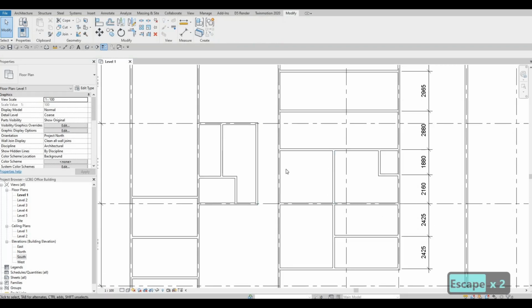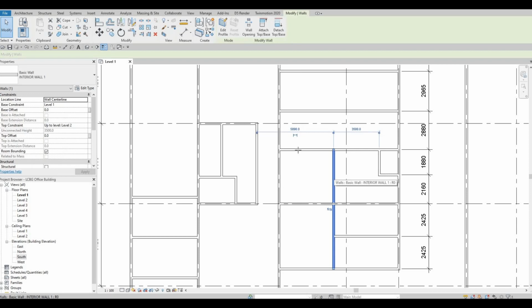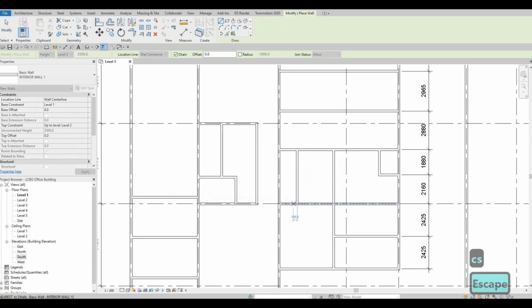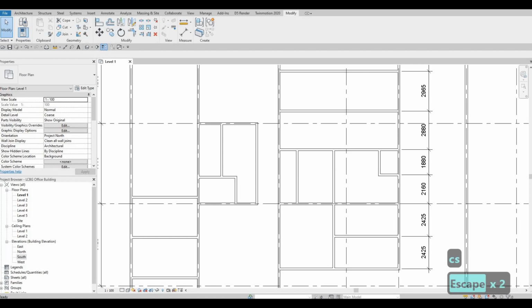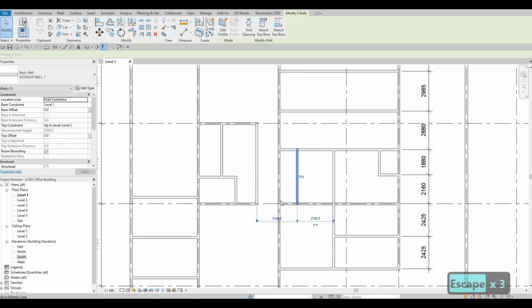Okay, so we could divide this into the washroom for women's and men's. Okay, and then we're gonna have a divider here. So CS, add a wall there, and that wall would be around. Let's move this to here. Around 1200 is good enough.